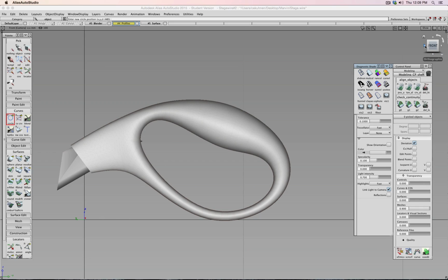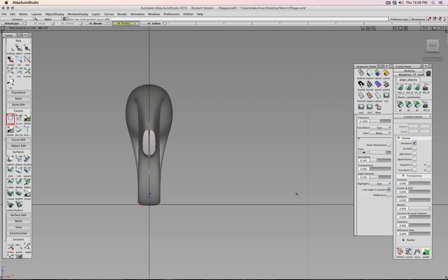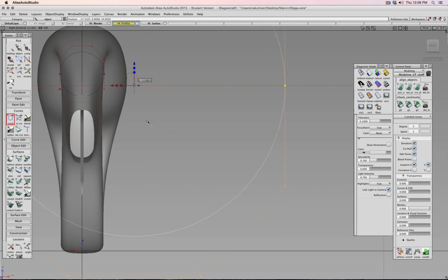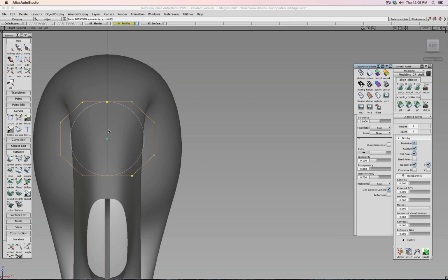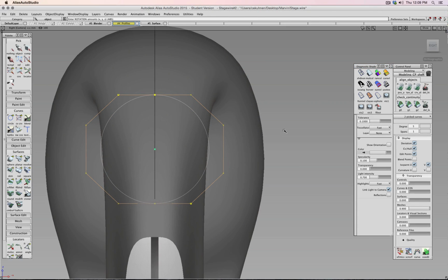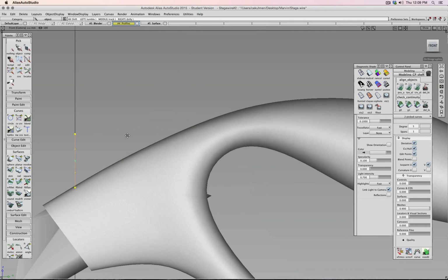Okay, so I go to this view, I hold the Alt key and snap it to the grid, move this one up, click on the cube to scale it down till I get the width. And then let's go to rotate, click the object, circle, and along the y-axis 0 spacebar 90, enter. Let's move, and I can continue scaling this a little bit, and let's go to side view, go to move, somewhere there,